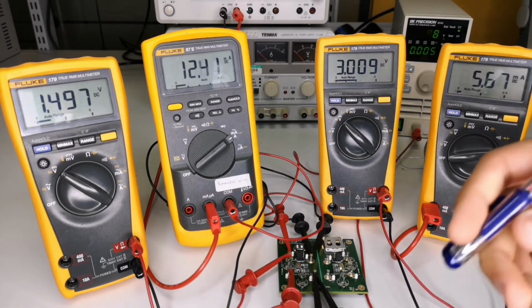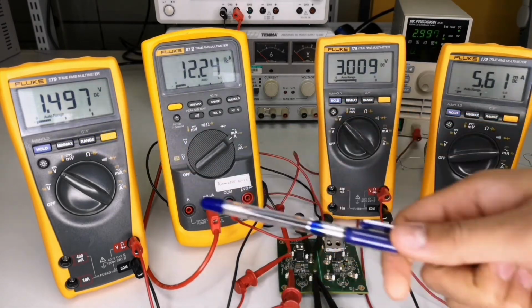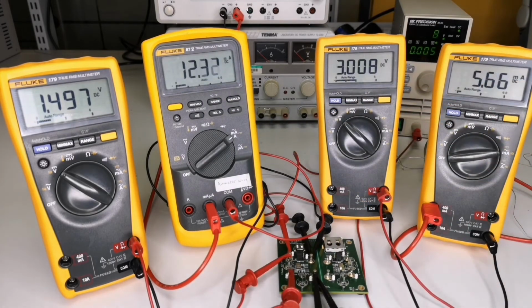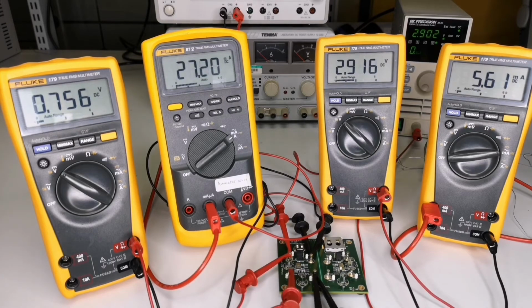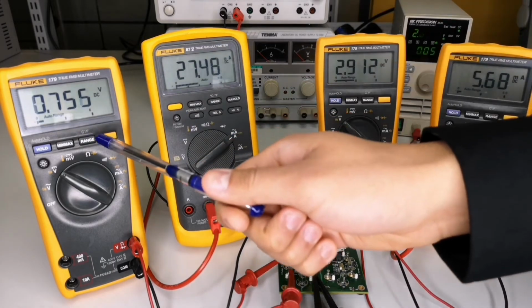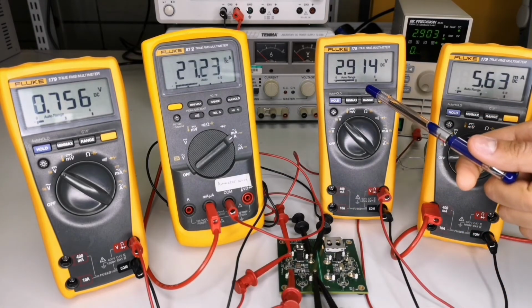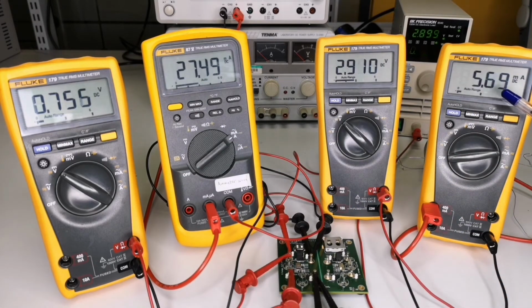Now, we can see the input voltage is 1.5 volts and the part is drawing approximately 12 milliamperes, and the output voltage is a steady 3 volts for an output current of roughly 6 milliamperes. Now, let's check the transient protection feature of the part by turning the input voltage down. You can see the part is still working for an input voltage below 0.8 volts, giving a steady output of 3 volts and an output current of 6 milliamperes.